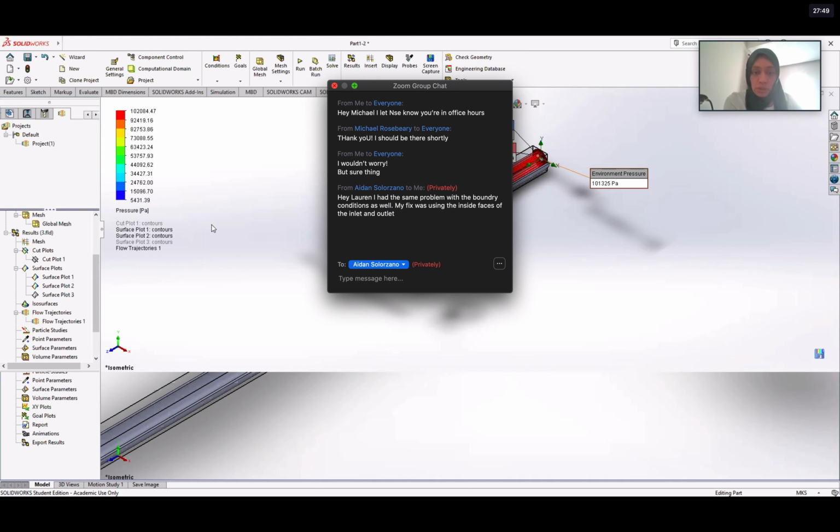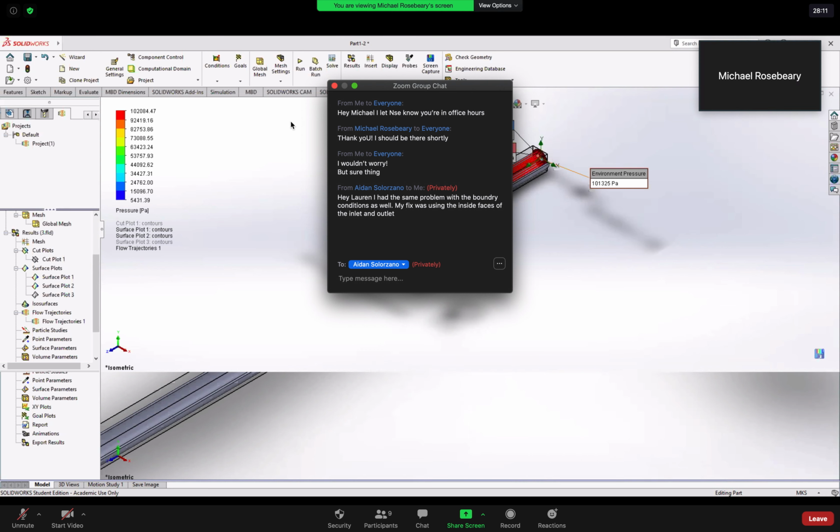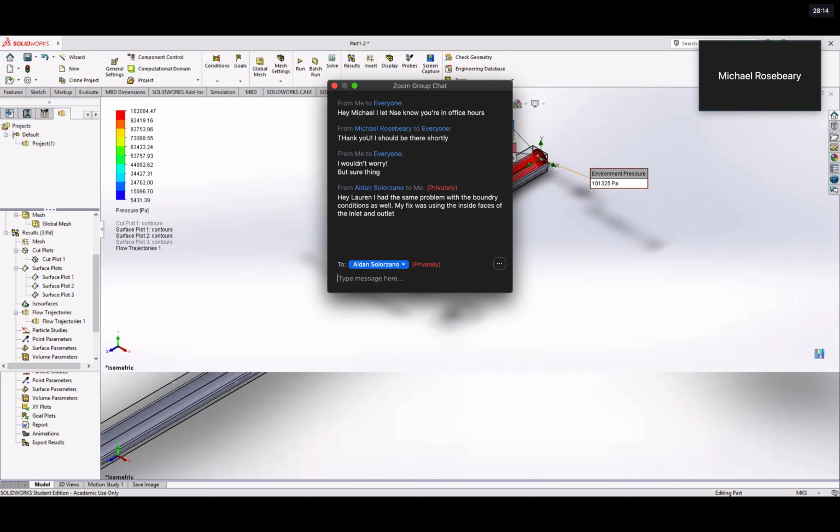So did you show the professor this result or not? Did he say that makes sense? I did show him all of these images, and he said this doesn't make sense. Yeah, he recommended I speak to you because he thought my inlet conditions were set up incorrectly. He said the flow should occur from the higher pressure inlet towards the lower pressure outlet. I think you may have set your inlet conditions incorrectly. He said the code should automatically develop a higher pressure at the inlet compared to the outlet, and the simulation should then become self-consistent. That's what he told me.